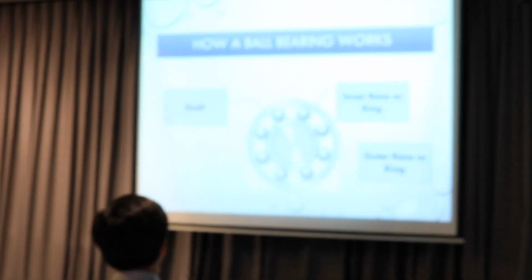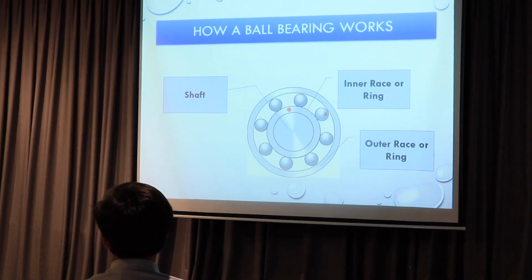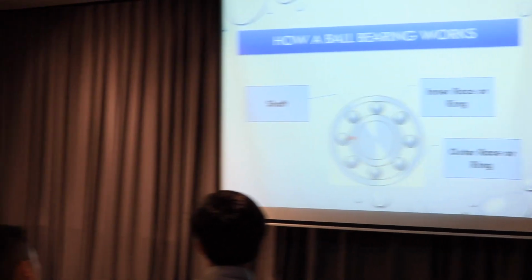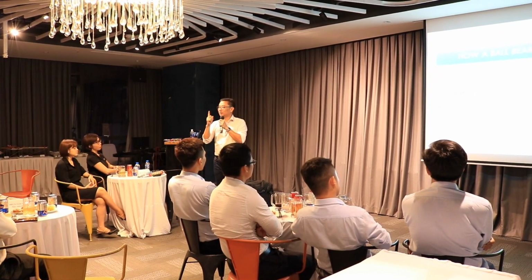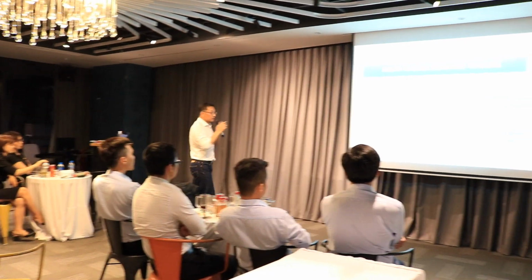A lot of technicians go into the field and someone says, hey, the bearing has no grease. You take the grease gun and you go to the pump. The whole grease gun, this big, and you finish all the grease on one bearing. So the question is, is it good? You have too much grease. A ball bearing must turn.